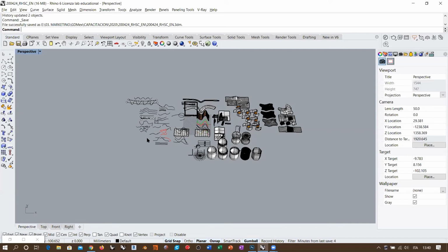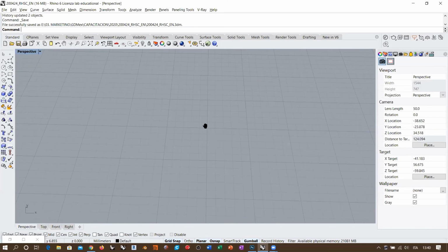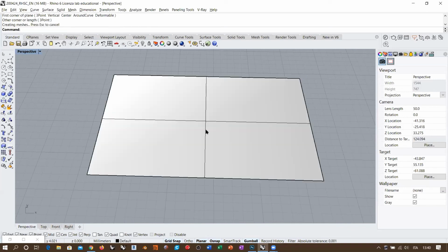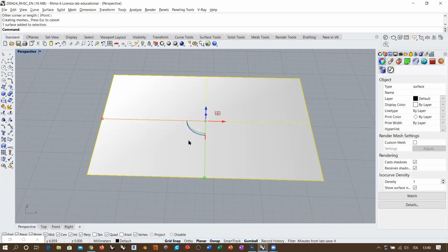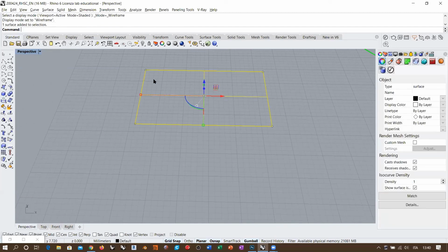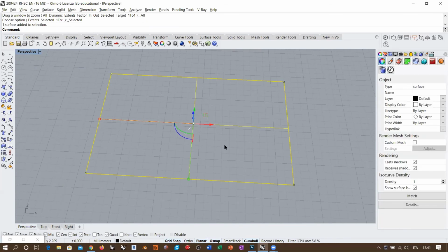So I'm going to make an example with a surface, and I'm going to deform my surface by controlling the knot spans. Eventually it will be clearer. So let's go here. Let's create a rectangular plane. So, a bilinear surface. It's not deformable inside because it only has these structural control points. I want to deform this surface from this edge up to a certain depth, and I want all the rest to stay untouched, and deform it organically. So the first thing you need to do is make this object deformable.